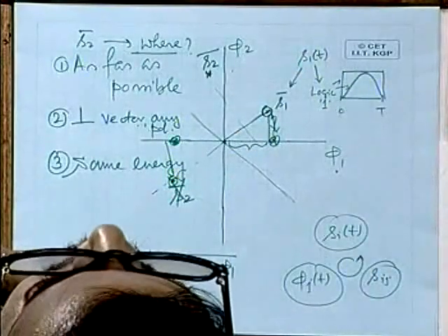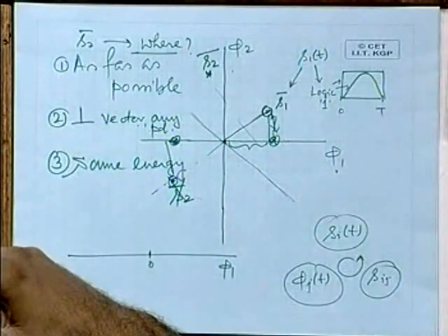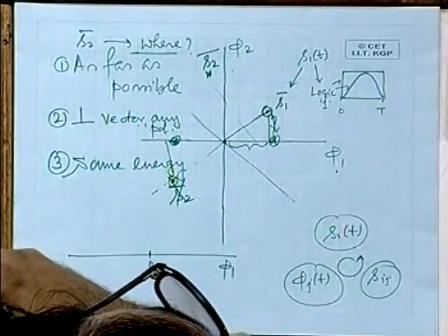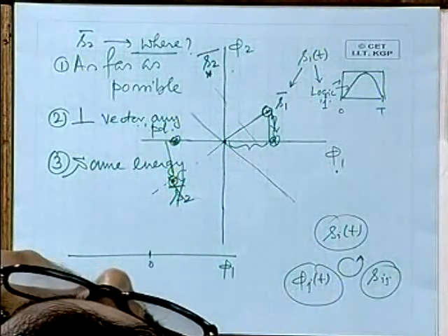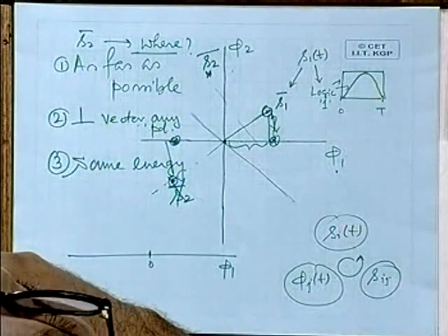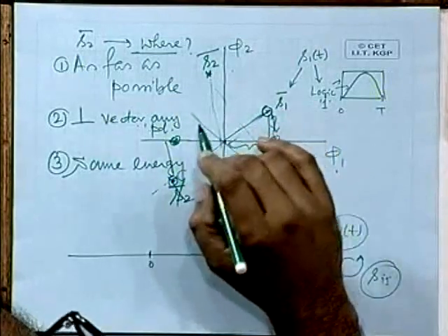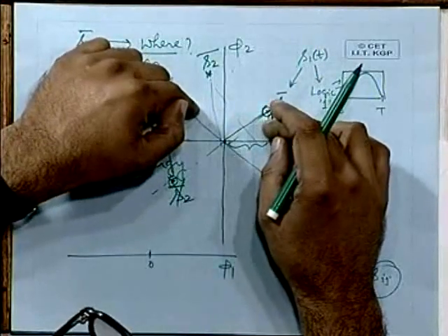Is it acceptable first of all as a modulation scheme? Yes, acceptable. Why not? Because both the signal points can be decomposed in terms of the basis functions, so they are acceptable. Yes, but it is not very good really. Because we can see that they have got different energies. So, one question would be, why is it that you are transmitting two symbols with different energy? How does it help you in the modulation scheme? Unless there is a special reason, there is no reason. You should not transmit that really. So, they should be transmitted with equal energy.